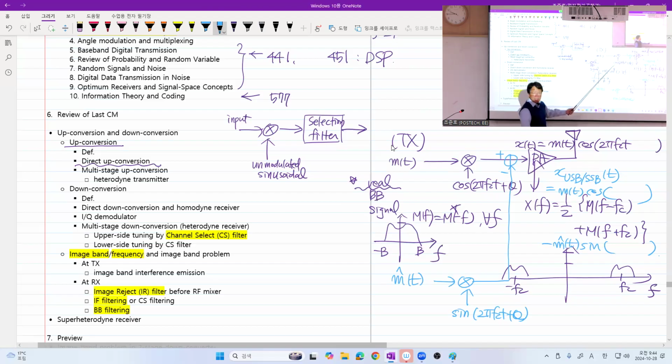this cosine signal itself may not have very stable frequency or very stable phase angle. Even though this has very stable frequency and phase angle, sometimes in the IQ modulator, by the way, this is sometimes called an IQ modulator or phase shift modulator, the sine signal may not have complete phase coherence with the cosine signal.